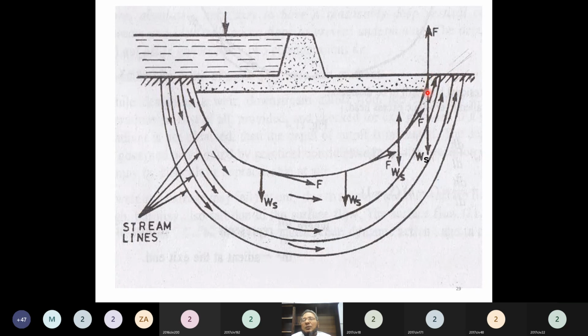That you know. And how much is the length? This you know. So this change in pressure over this length would be the exit gradient. The slope that comes out, that is called the exit gradient: change in pressure with respect to change in length. All right. Yes, sir, it's clear. Thanks.